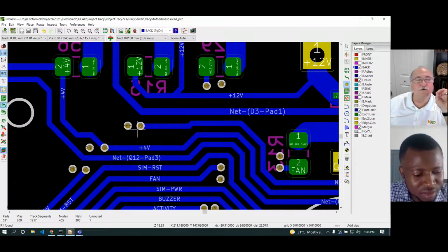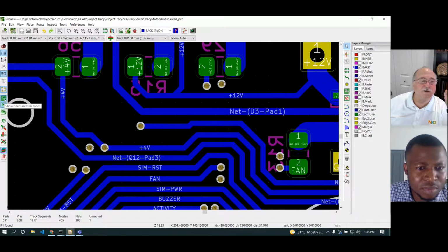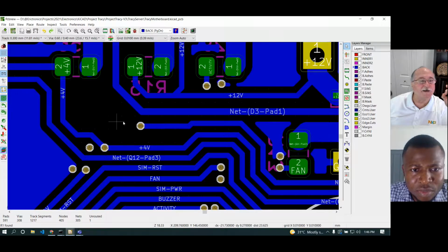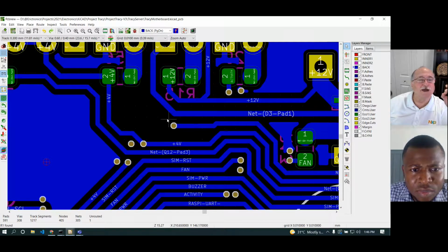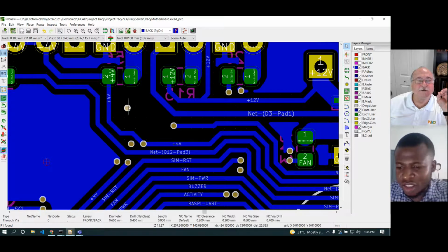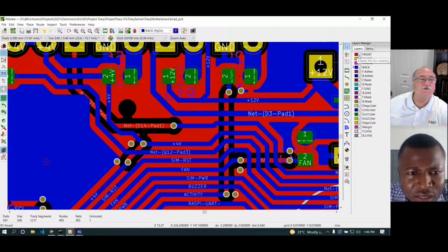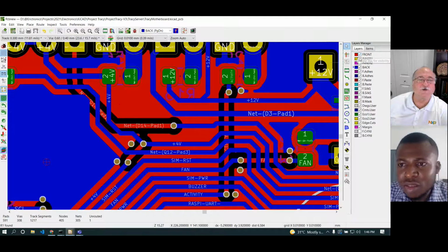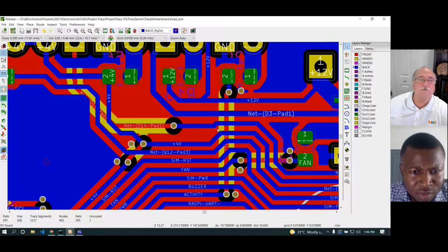What I try to do is encourage people to place the vias so that the annular ring, the keep out area, overlap. That makes it so you can't route between them, and you have the best path between the dielectrics, between the top and the bottom of the board. Sometimes it means you have to move things around a little bit in order to clear a path. So a via fits very well in the left-hand quadrant about the 10 o'clock position. Yeah, but move it closer.